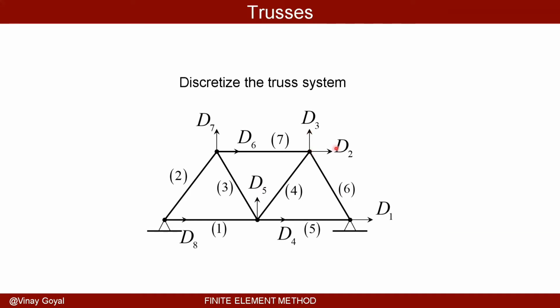Clearly, you can see that in this scenario this node can move both ways. This node can move both ways. This node can move both ways, and there's an error here. It's not showing the circles. There are 2 circles here representing a roller, which allows this point to move left or right. And that's why you see a degree of freedom there as well. This node also was supposed to have rollers, and it's not showing up. But trust me, this can also move left or right if you were to have a roller.